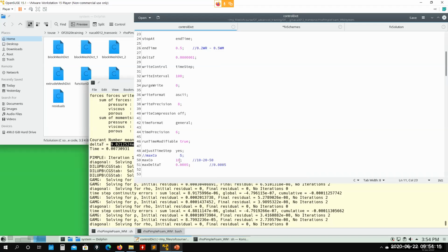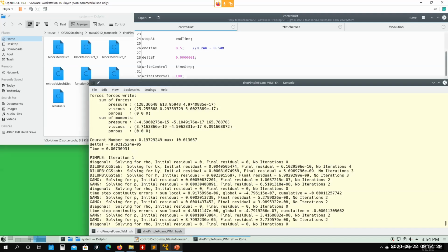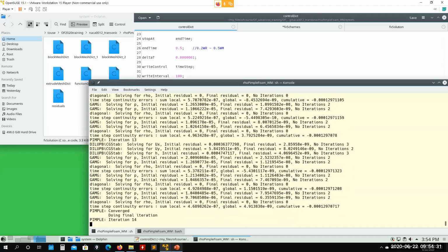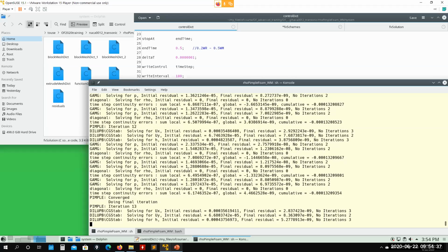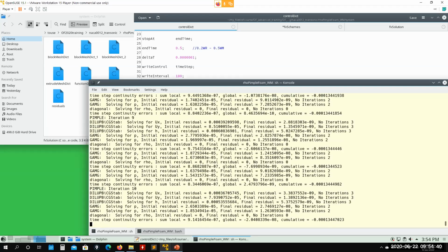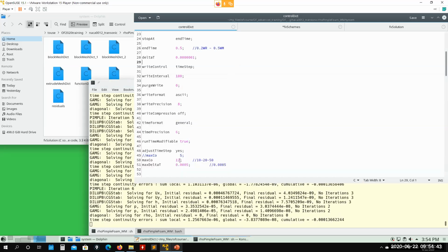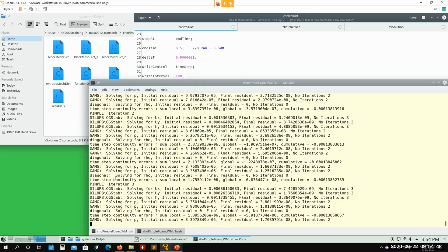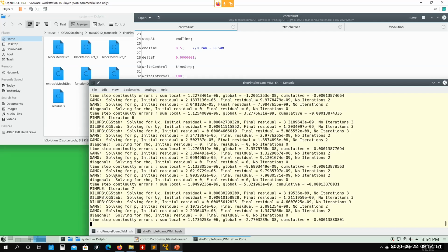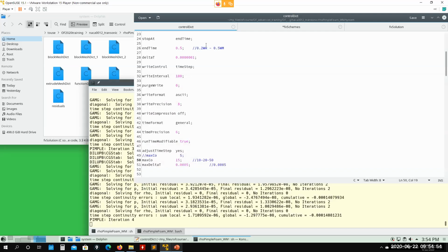Let me go. And this is very important advice. Do not put 20 right away because it's likely, probable, that it will diverge. So you need to do these increments in CFL slowly. So I go 12. I let it run a couple of iterations. See that now it will be increased. Let it run a couple of iterations until it settles. And then you go 14, 16 until you reach the decided CFL. So now I go here 15. So do these changes, you can do it on the fly. I hope you know that one, but do it very slowly.